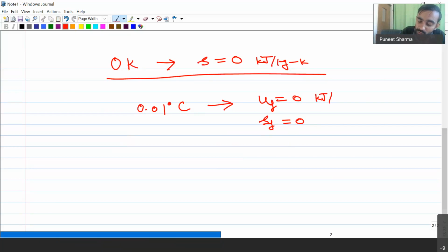If you go to the refrigeration table, refrigerant is another working fluid which is used in our refrigeration cycles and devices. For each and every refrigerant, you will find some different reference point in the property tables. While doing our analysis, we have to obtain all the values with reference to a single reference point.